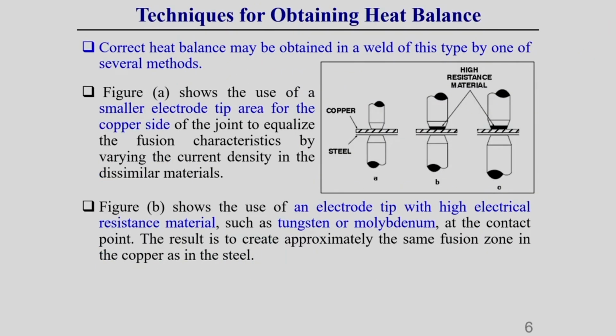Like, let us say two different plates, the top one made of copper and the below one made of steel. Now, what we are discussing, let this be copper and this be our steel. As this copper has very high thermal conductivity, heat can dissipate easily, and its resistance is also less, that is why localized heating will generally be less.